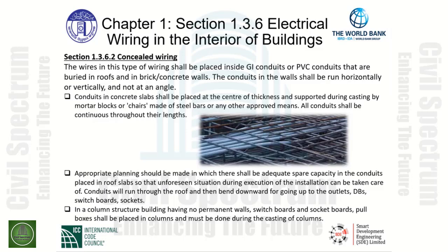Conduits in concrete slabs shall be placed at the center of thickness and supported during casting by mortar blocks or chairs made of steel bars or any other approved means. All conduits shall be continuous through their lengths. This particular area mandates that the conduits be placed in the center thickness of the concrete, and they must be supported to that elevation with steel bars, chairs, mortar blocks, or any other approved means.